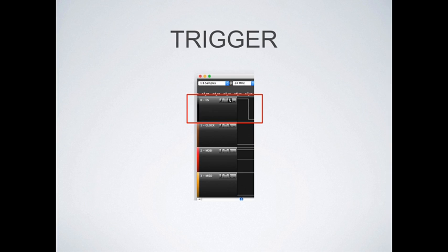There's probably only one SPI interface coming off of your microcontroller, and it's going out to several slaves. Your microcontroller can be talking to other slaves, but I really don't care about those. All I care about is the CC3100, so I connected my black channel to the chip select of the CC3100. I want to know when that chip gets selected, then I want to start sampling data. That's my trigger, and I'm waiting for it.